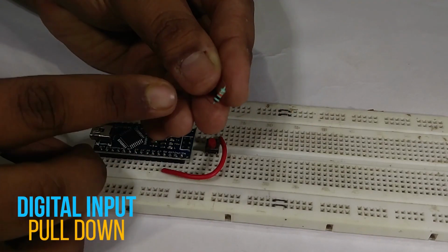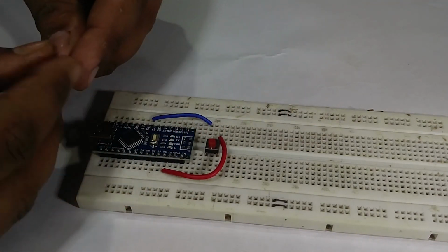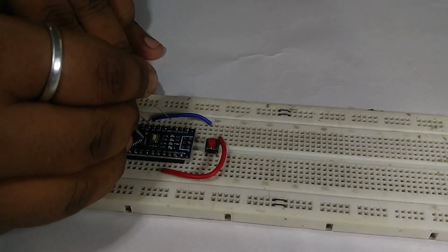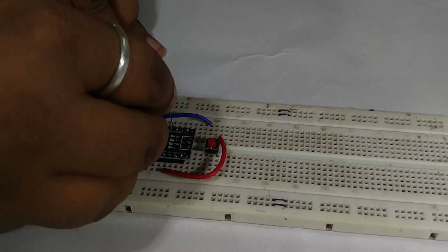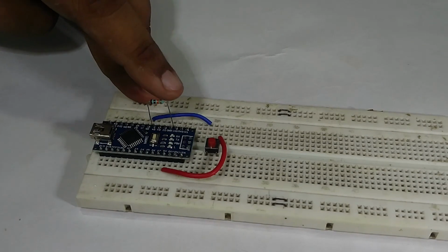Now we will connect a 10 kilo ohm resistor in between the pin, which is D5 in our case, and the ground. So this arrangement is a pull down arrangement.